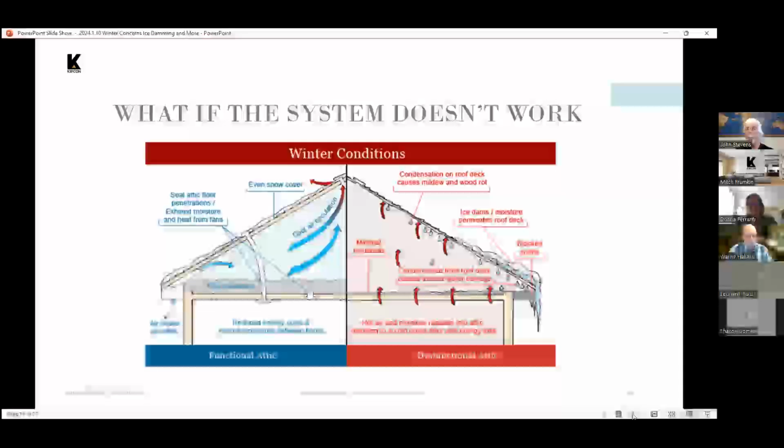The other thing that is important is making sure that any penetrations into the attic are properly sealed, and that, again, as I spoke earlier about vents, such as bathroom vents, are exhausted directly to the outside. You have a functional attic. You have cool air circulation, no condensation, no moisture, and the attic will function properly.